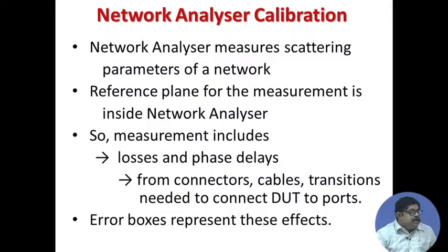So, these extra connections, connectors and cables shift the reference plane, and that is why the measurement includes the loss and phase delays that are obviously present in any cable, connector, etc. And so, there is some error in the measurement.